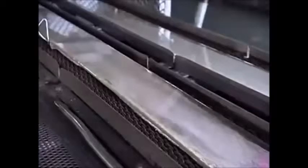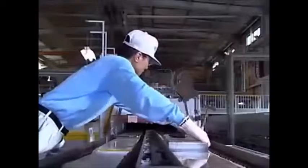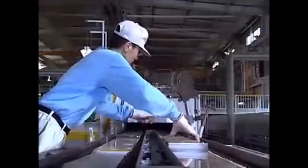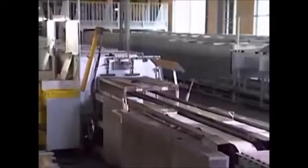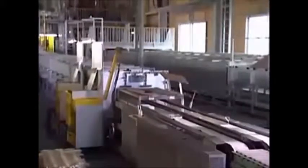This sheet is gradually cooled to room temperature while traveling on a conveyor belt through a temperature gradient type continuous slow cooling furnace. The sheet glass produced by this process is used as the material for individual lenses. In high-quality optical glass production, the fusing and cooling processes are the most important.